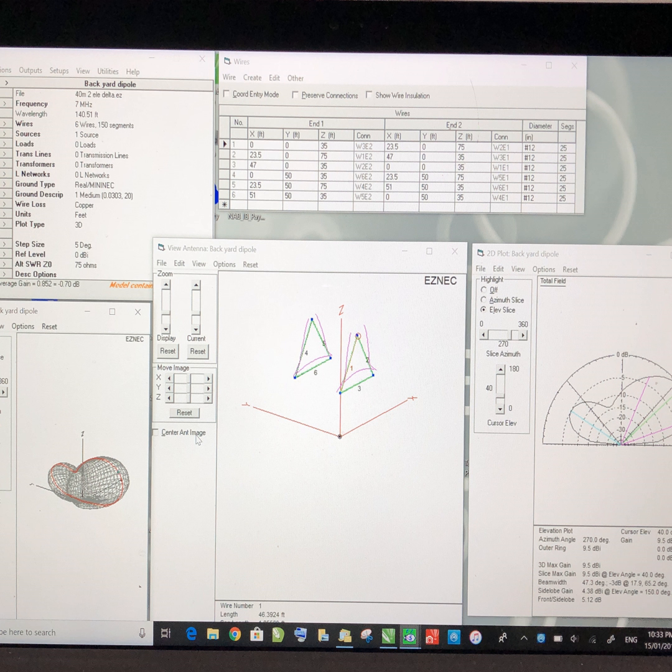At the ends of the wires you need some sort of insulator. These can be the generic black insulators that work quite well. You can use polycarbonate insulators. They actually work very well. You can buy sheets of polycarbonate. You can cut this up, drill some holes, whether it's clear polycarbonate, white polycarbonate, or black, it all works pretty much the same. It's a pretty good insulator at HF frequencies.